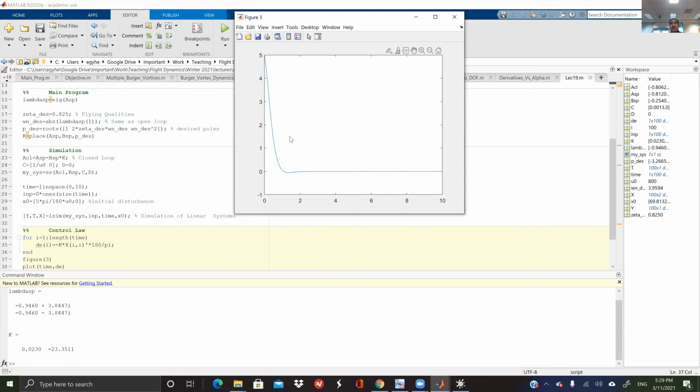And this is a consequence of a large gain. When you have large gain, it's not smart to have all the poles at -100, having your settling time in 0.01 second or 0.04 seconds. It's not smart. Why? Because you will not simply be able to achieve it. You can achieve it theoretically, only theoretically, but when you go and implement it, the required control action, the elevator, will be too large. So your servo will not provide it, and as a result, you will not get this performance.